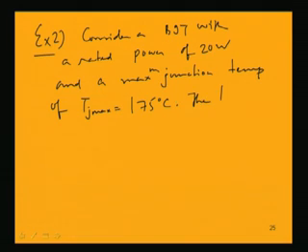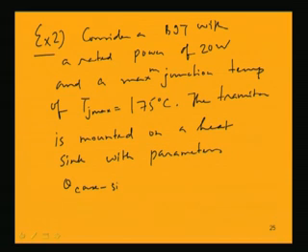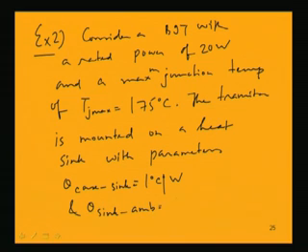The transistor is mounted on a heat sink with parameters theta case to sink thermal resistance is given as 1 degree centigrade per watt and theta sink to ambient is 5 degree centigrade per watt.